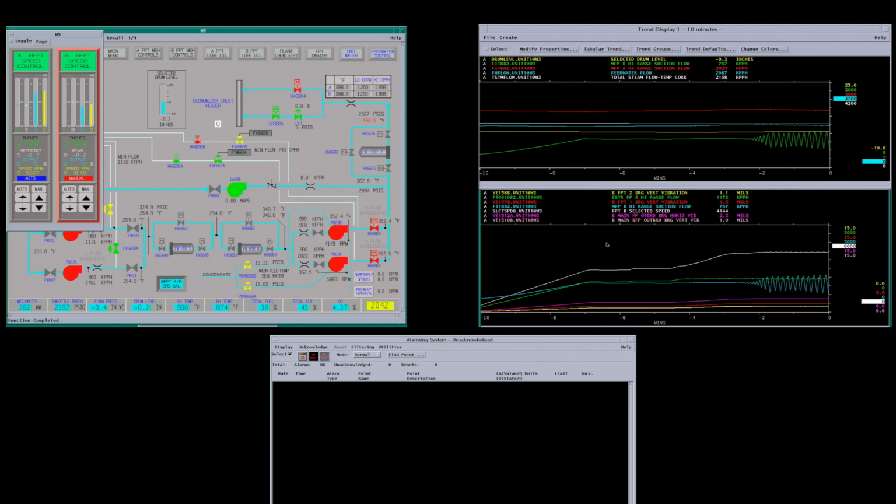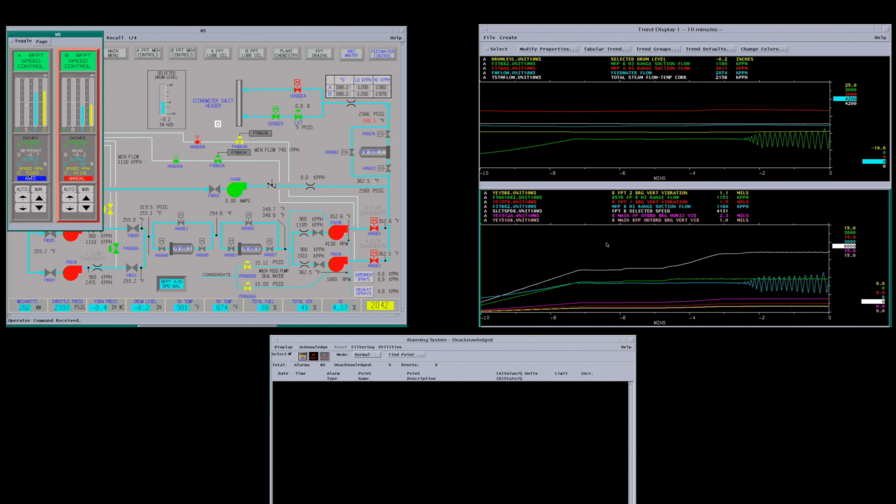So to get out of this situation, you need to get out of this flow range. On this screen we have the recirc on the booster pumps open and also the recirc on the main pump. The A pump is running about 5,000 RPM. The B pump's running 4,100. So we're going to get out of the cavitation. Now we're going to go ahead and start driving this pump up. This should run up pretty fast. You just hold down the manual button and drive it up quick to get out of here.